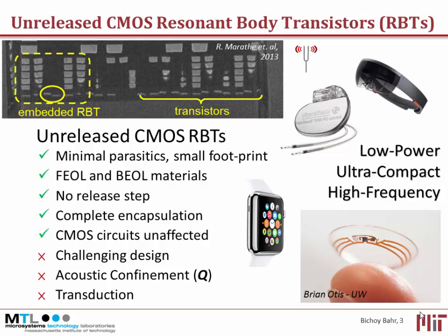And so this, of course, allows us to minimize the parasitics in routing to nearby circuits. It also gives us access to the high quality materials available in the CMOS process, especially the silicon substrate and the polysilicon layer. With this, we also have access to the small feature size provided by the CMOS technology, which allows us to easily scale to gigahertz frequency while hopefully achieving a high quality factor.